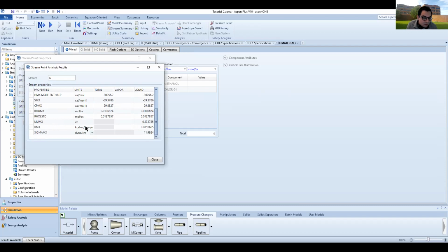Okay, that's in kilocalorie meter hours, so in these calorific units, but if you want them in joule second meter, just change your units from here and you get 0.09. Okay, and then you're being asked for the molar density, just look for the molar density from here, you're going to find it.